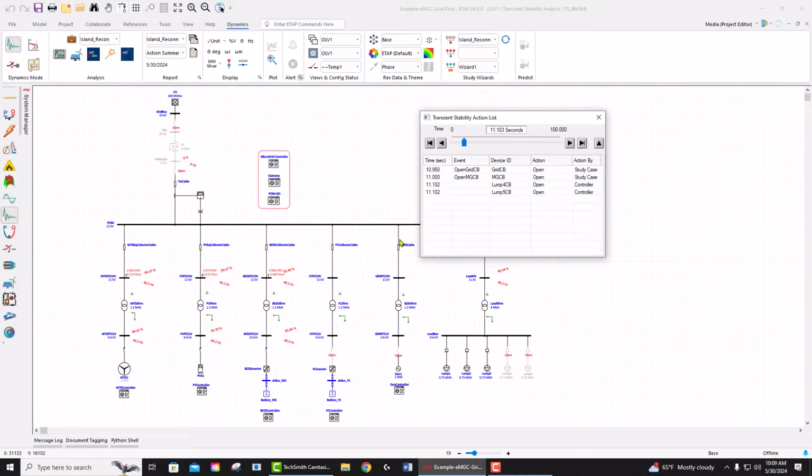At this point, the microgrid controller has already done the analysis beforehand and is going to shed some loads. It switches the battery to grid forming to make sure that the system can transition to the islanded mode. And then it tries to bring in the generator and then the fuel cell to the system. As you see, the fuel cell and generator are back. One load is restored, and then the second load is back. So all the loads are back to the system. System runs in the islanded mode.